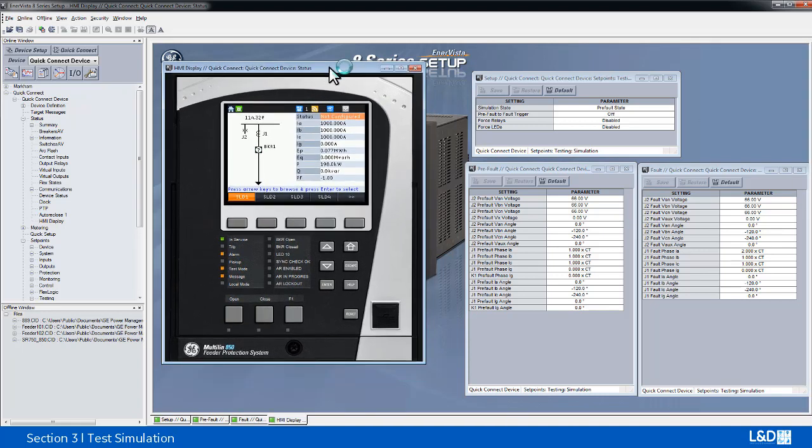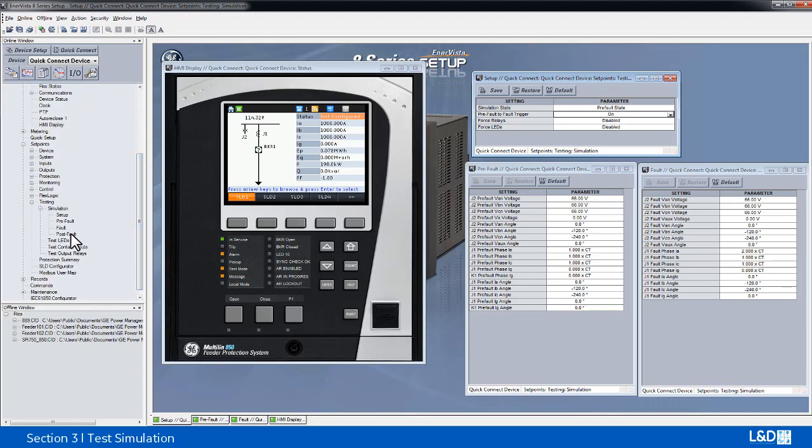So the next test we want to do is the pre-fault to fault trigger by using manually turn on. This can also be done by using the contact inputs, virtual inputs, remote inputs, or any other FlexLogic operand. For this demo, we're just using manually turn this on, and we're going to click Save. As soon as I click Save, this pre-fault stage will jump into the fault, which means 2 times CT. And also, when the relay operated, it will jump into the post-fault.